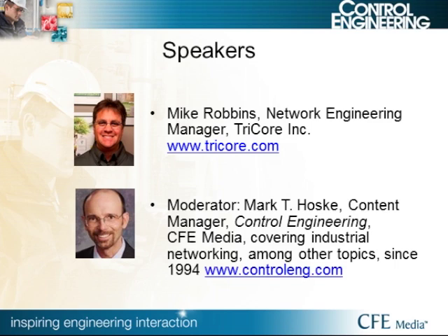The 1005 standard turns it back to the way it was and says put small industrial switches in the control panels or near the devices, and then run fiber or shielded Ethernet cable back to a switch if you're going to a server room somewhere or a server rack. That 1005 standard does change up the thinking about how to design and implement that network.